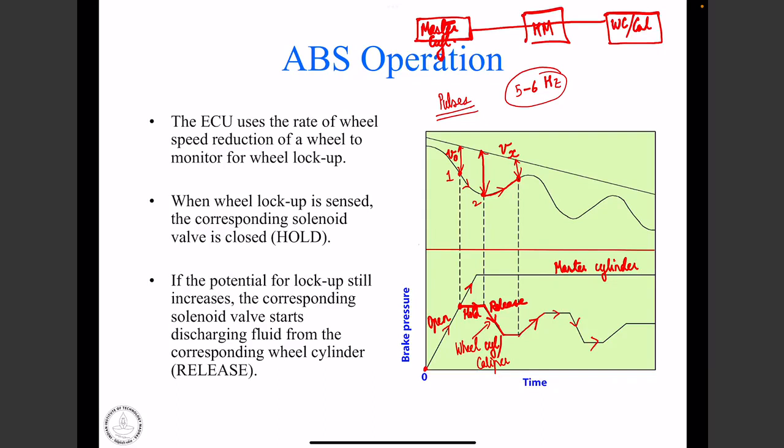So it becomes very interesting to study braking. That's why I started off with braking, because as we discussed, the brake system is the single most important safety system available in the vehicle, and we should ensure that it is able to brake the vehicle in a stable manner. It is typically designed such that when the brake is fully pressed, we command the maximum possible deceleration.